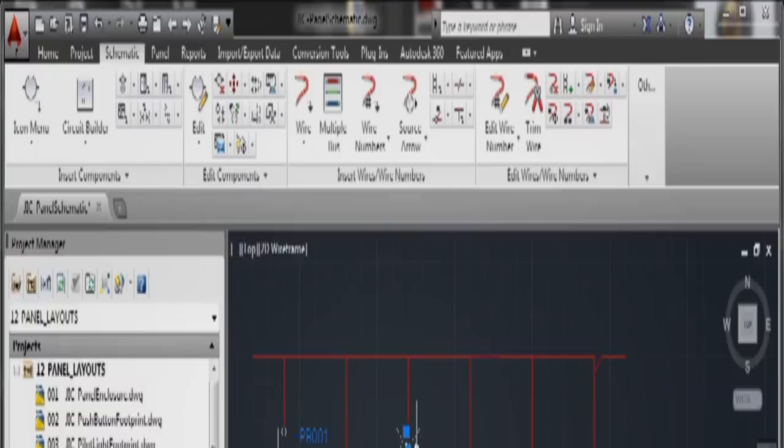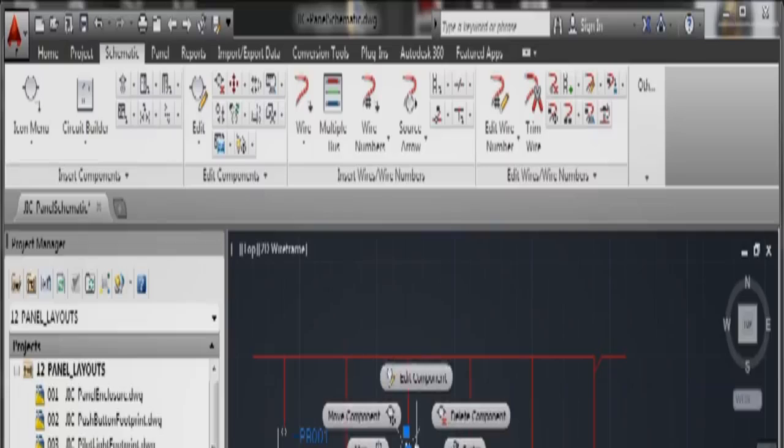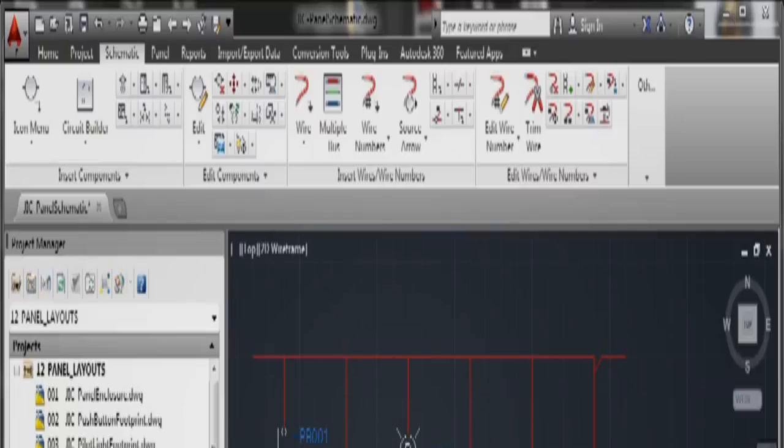So what I'll do is I'll click there, right-click, attribute, and move the attribute. It's asking me to select the attribute to move or pick on the block graphics for list. I'm going to click on that one there. Again, you might want to take snap and grid off when you do this. It makes life a little bit easier. Click there. Right-click to confirm, click for base point, and I'm going to place that there. Much neater, and then press enter to finish. It just tidies up the drawing.